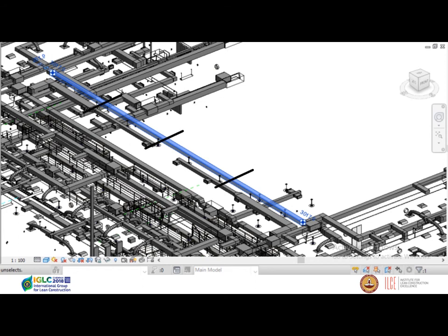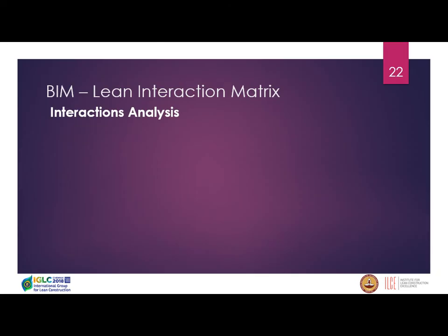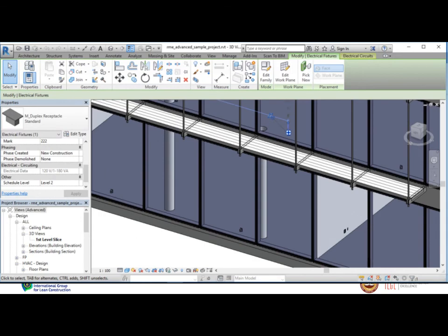This duct is around 30 meters tall, and if you model it in Revit, it won't say anything because there is nothing wrong. But in reality, there is not a 30-meter duct that can be used once. It must be assembled from pieces. Another thing is one of the BIM authoring tools, Revit, allows you to have electrical conduit in the glass of the panel, which is unrealistic.